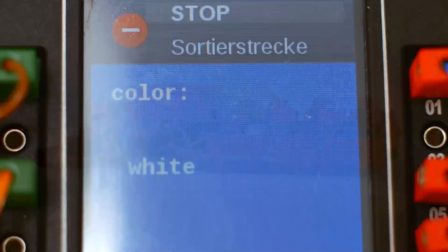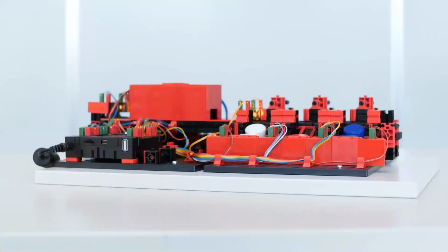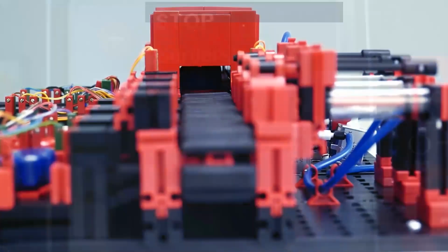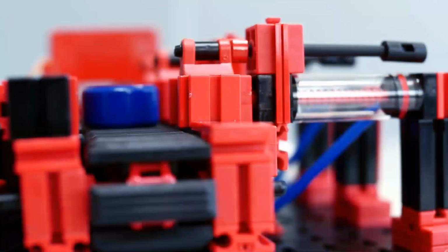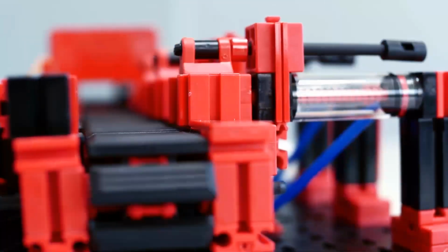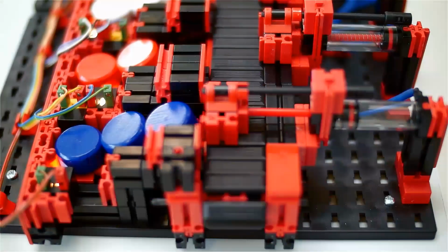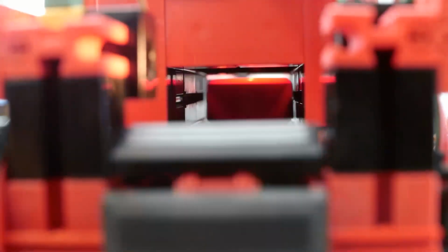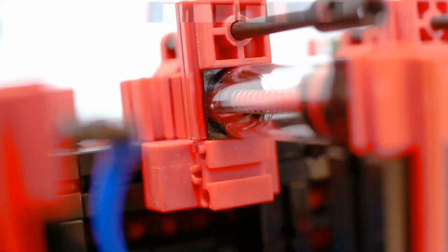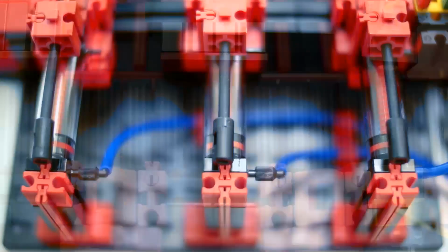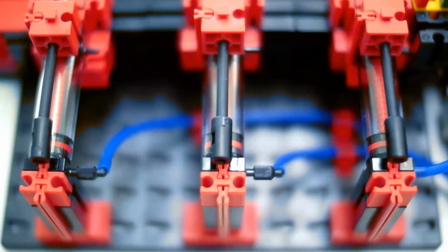The dimensions for this model are approximately 20 by 14 by 12 inches with a weight of about 10 pounds. Now, as with the models we've looked at before, the 24-volt version has a relay board for motor polarity reversal and both a multi-pin connector, again 26 pins with a grid of 2.54 millimeters, as well as additional PCB terminals with pushing connections for all inputs and outputs. Again, you will need to provide the PLC and the programming. The 9-volt version again comes pre-wired to a pre-programmed TXT controller, and one 120-volt power adapter is required.